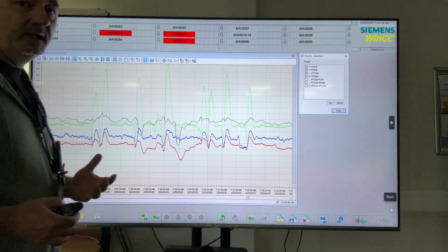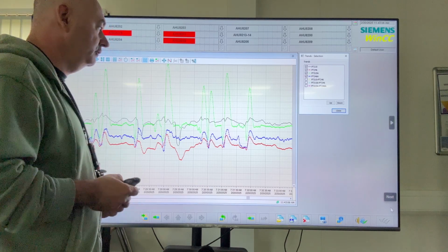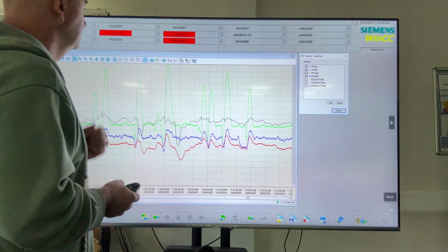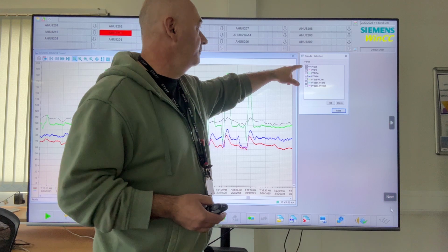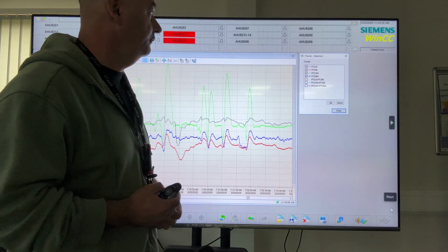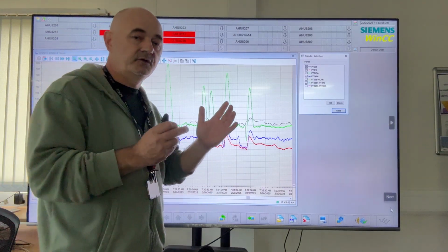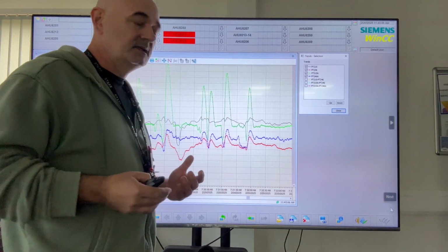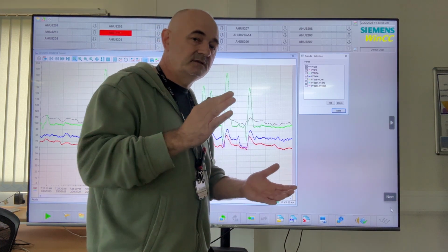Because I like to deal with causes, not with the effects. When we do root cause analysis, we have to understand the causes, what creates issues. In this example, I'm not sure if you see it very clearly, but I have rooms P215, P246, P215A, and P246A, where the tunnels create a lot of problems. And because FEMS looks only at the pressure difference between the rooms, I created a system in which all these rooms are related to the atmospheric, and the difference is calculated after.